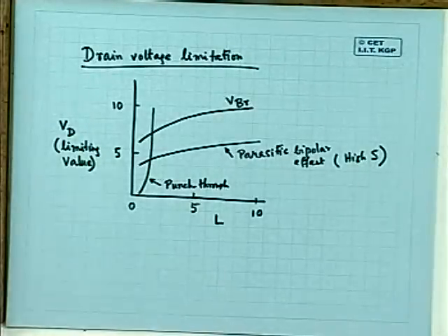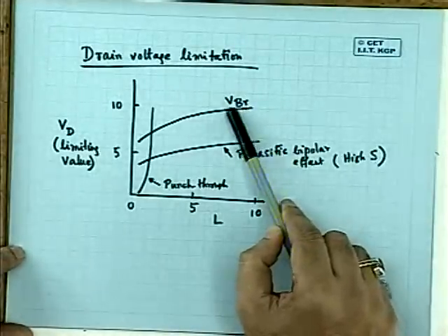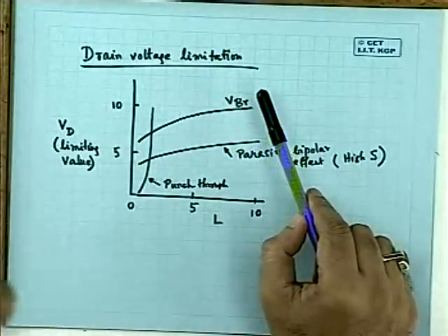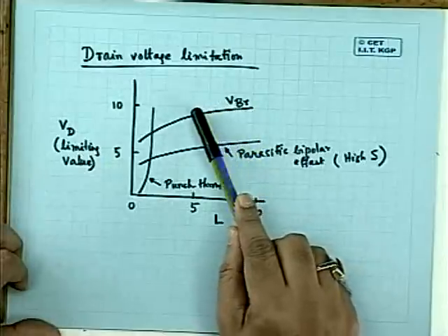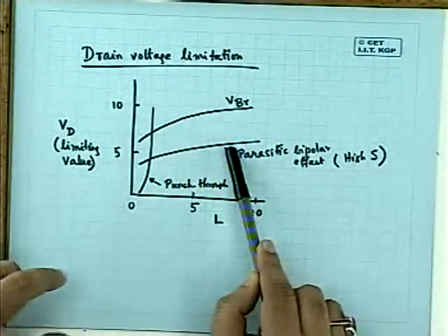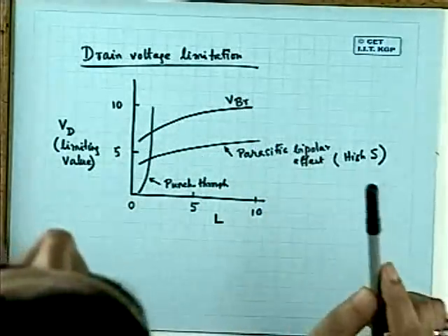It is found that as you reduce the L value, the breakdown voltage is also slightly reduced, due to avalanche breakdown, because the combined gate, drain and source come in, and due to curvature effect, etc. It is found the breakdown voltage of the drain junction is also slightly reduced, as indicated here. You should never go above that. Your drain bias should never be above VBR.